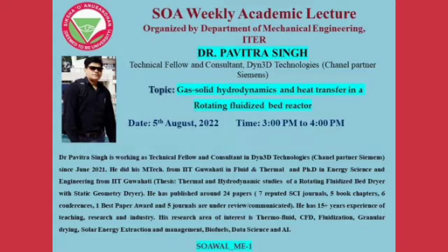And during the experimentation we need to calculate the percentage of moisture at a certain time interval. So I have selected a time interval of 5 minutes. So I have taken the samples every 5 minutes. So we can calculate this moisture content percentage on wet basis and on dry basis.